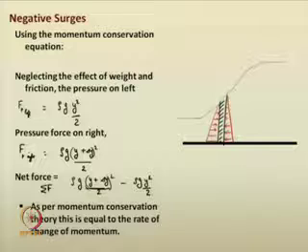Now, this net force should be equal to the rate of change of momentum, which is the rate of change of momentum stored inside that elemental strip plus the net outflux of momentum through the control surfaces, as per your Reynolds transport theorem, you remember them. So we are using the same theory here.